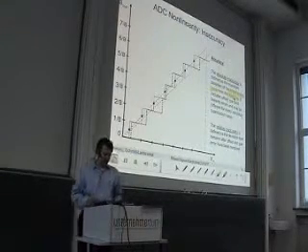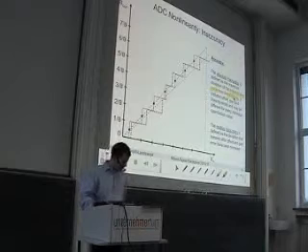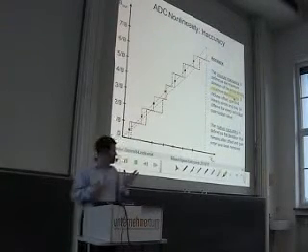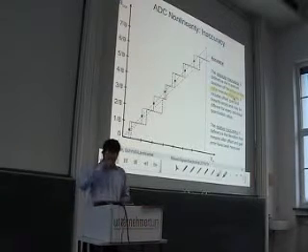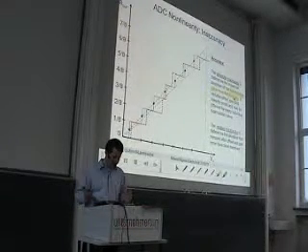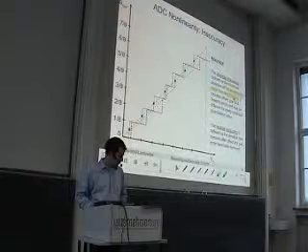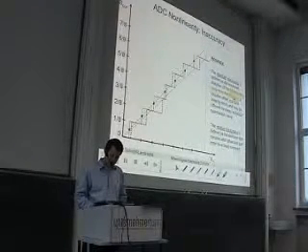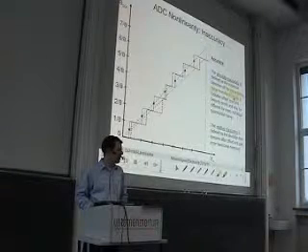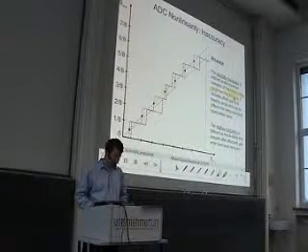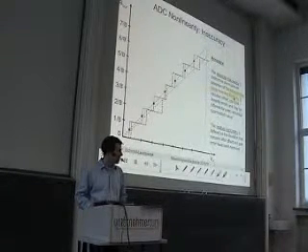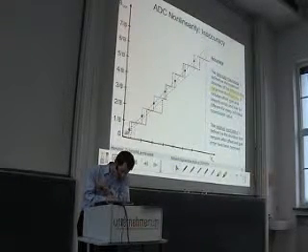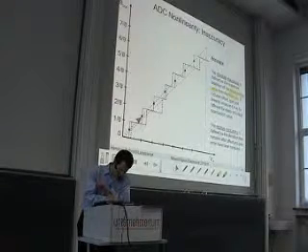So the black curve is the ideal 3-bit ADC characteristics. And now we measure an ADC that we want to characterize, and for instance we get the red curve. So the deviation of the analog value from the ideal one. So we take always the midpoint of the steps. So we take these points that are indicated here.